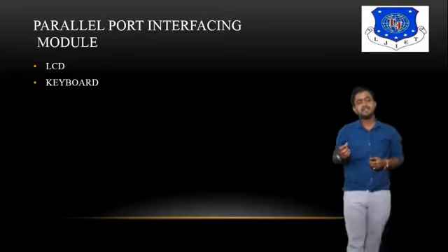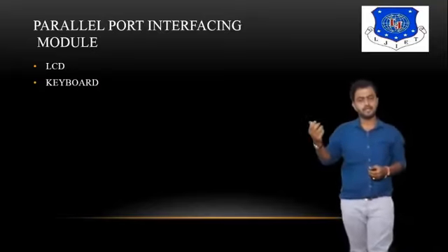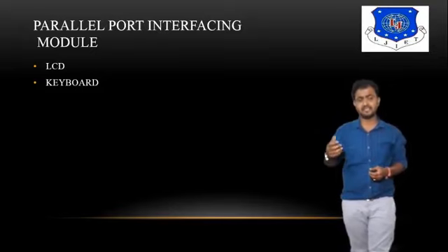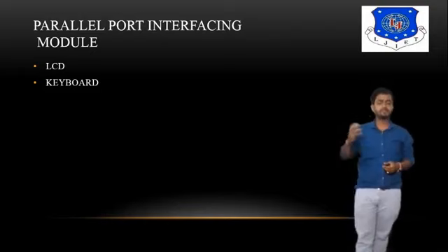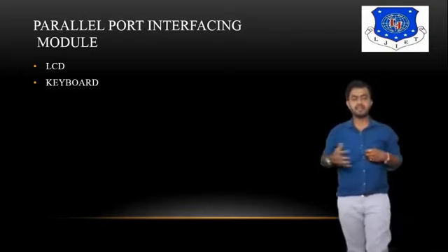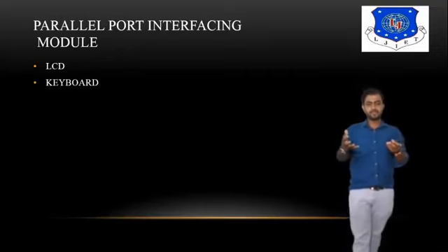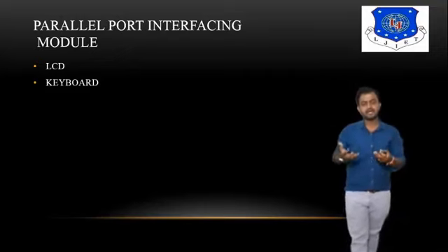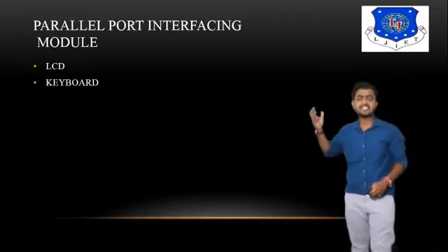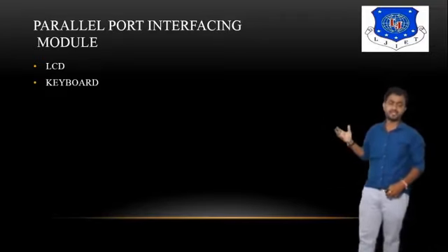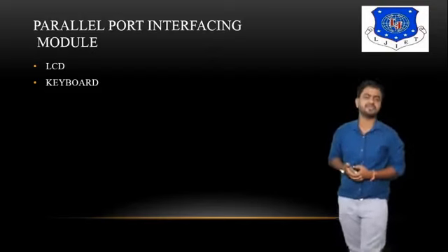And it is used in two ways. Some modules are used in what we can call control mode, and some in what we can call data mode. In terms of the data mode, it generally uses a handshaking based approach. In the handshaking based approach, it transmits the data through the data pins, and according to the control pin operation, it will control the data rate. So basically, the LCD is one of the best examples of parallel communication. Right now, we use an 8-bit data mode or 4-bit data mode for the communication.